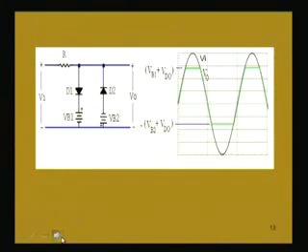So, now we can draw this output voltage waveform versus the input voltage waveform. Input is this black one, Vi, and if we now find out and plot Vo, starting with 0, when the input voltage half cycle is positive and the input voltage is less than VB1 plus VD naught, the diode does not conduct. When the diode does not conduct, this voltage is the same as the input voltage, because there is no conduction of current and there is no drop here. This point and this point do not have a difference in potential.